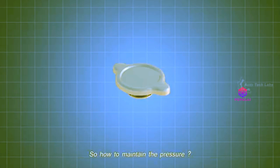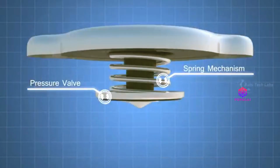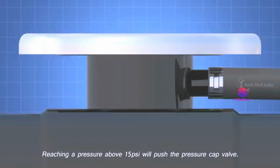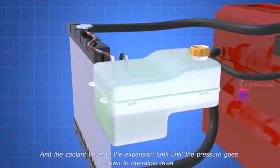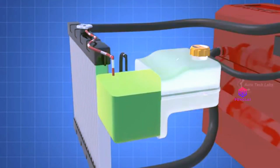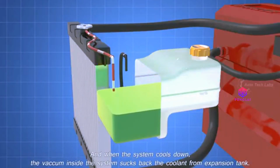So, how to maintain the pressure? Here comes the role of the radiator pressure cap. It consists of a spring-loaded valve mechanism, which will respond to higher pressure. Reaching a pressure above 15 psi will push the pressure cap valve, and the coolant flows to the expansion tank, until the pressure goes down to operation level. And when the system cools down, the vacuum inside the system sucks back the coolant from expansion tank.